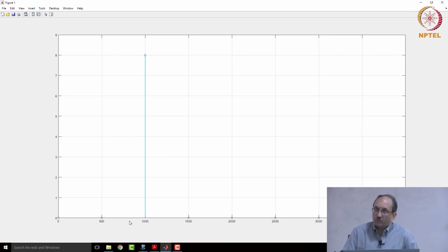So, we will continue this example in the next class. We will see why the other values are 0 here, and then what we will also do is sample the DFT more finely. Right now we have sampled it only at 16 points, we had a 16 point sequence and a 16 point transform. Now, we will zero pad and get the DFT by zero padding, and then overlay those plots on this and see the connection. Then we will compare this with the DTFT, and convince ourselves that the DFT is indeed the samples of the DTFT.